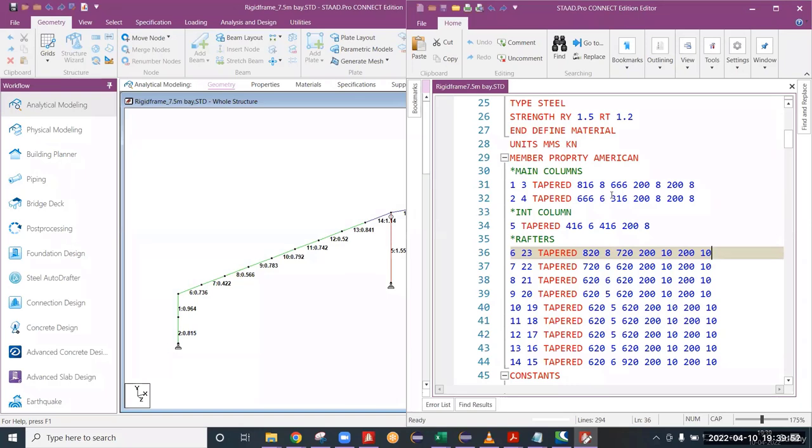If you increase the thickness of any member, the weight will increase. That is why we have to pass the member by changing the depths only, to the maximum extent. By providing depths only, we have to try to pass the section.